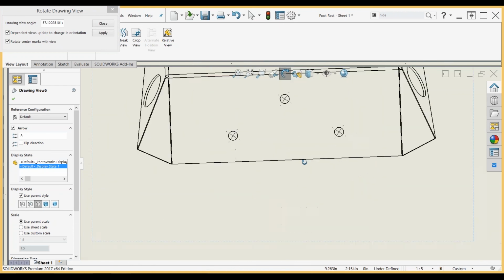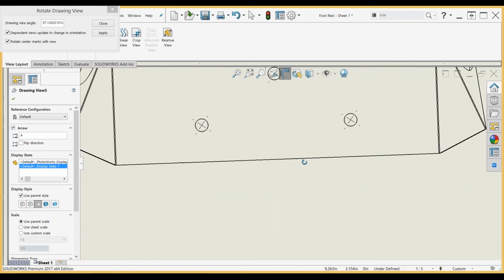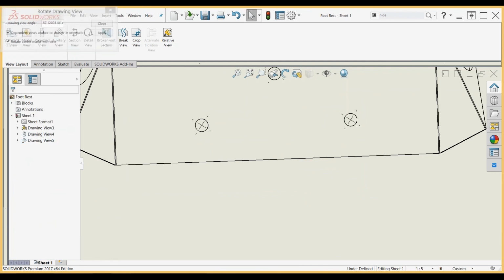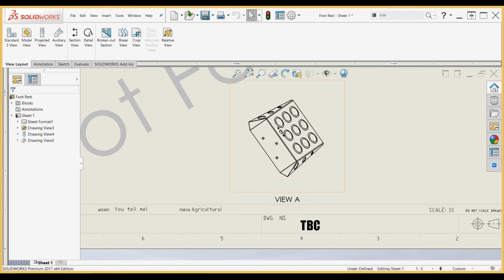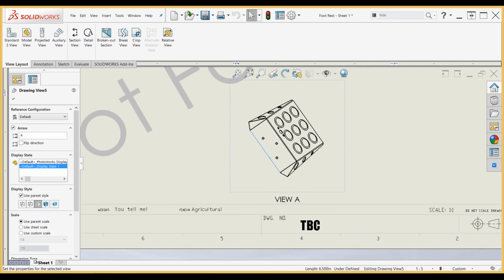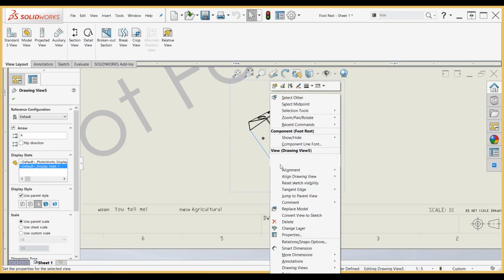Back to my orientation bar here, I have the option to create a new view. And I'm going to call it side holes. And this view that I create is going to be accessible in my view palette on the drawing file, as well as the orientation bar in the property manager of all of my views. So I'm going to save my part file.